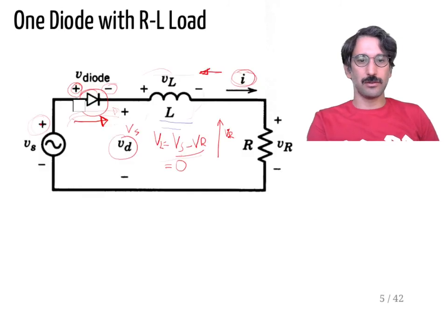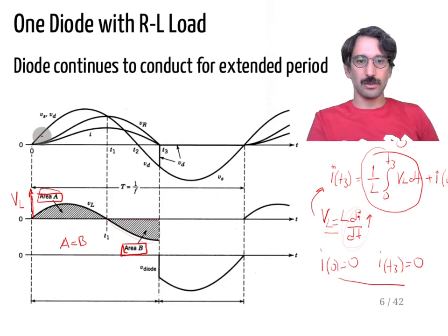So now let's look at what is the effect on the output voltage. Output voltage is basically VD, and that VD voltage is equal to Vs whenever the diode is conducting. So my output voltage is not across the resistive load, but this is my output voltage. So it is equal to Vs whenever the diode is on. So let me try to draw my VD. If it were a resistive load, I would have only half of the waveform, but now due to the inductive load, I see a short amount of negative voltage in my output waveform.